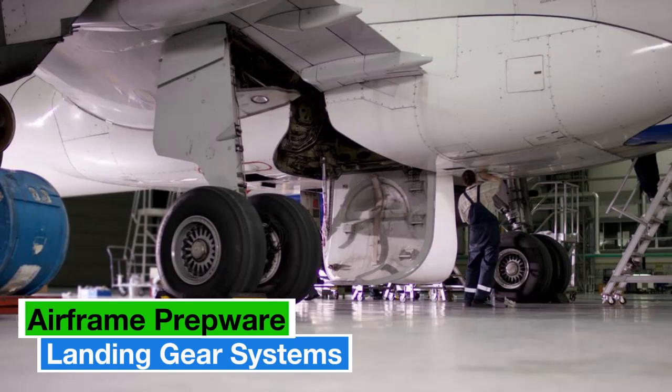A special bolt in a landing gear attachment requires a torque value of 440 inch-pounds. How many foot-pounds are required? 36.6. How long should you wait after a flight before checking tire pressure? At least 2 hours, 3 hours in hot weather.